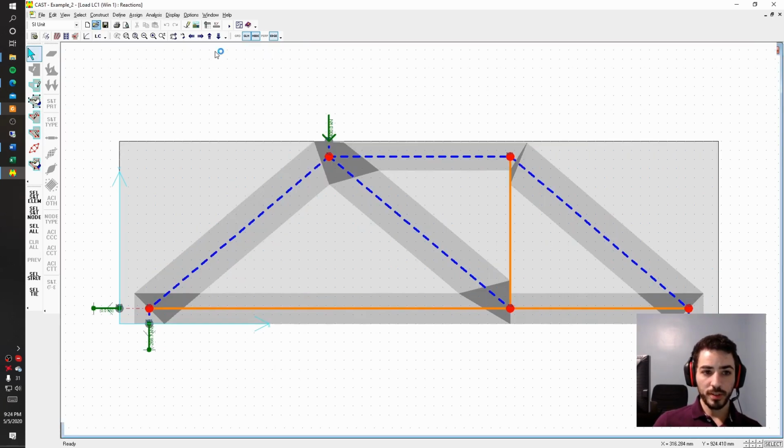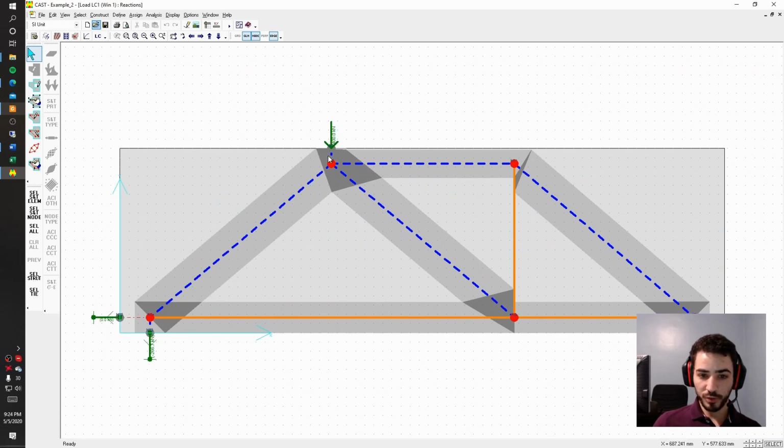So this model is exactly the previous one, with the difference that I broke this strut that was going straight to the support into two struts connected by a tie. And then I used the same rules to define the widths of each strut right here.